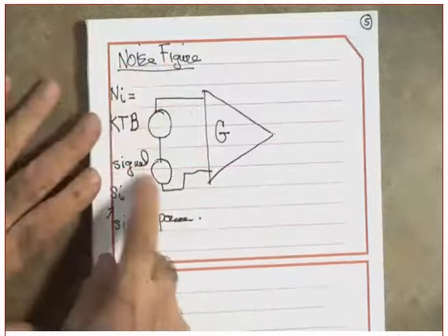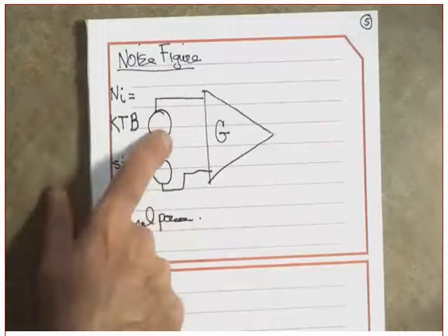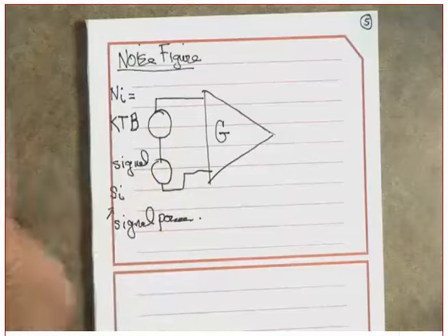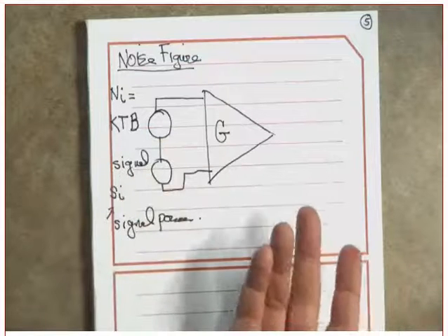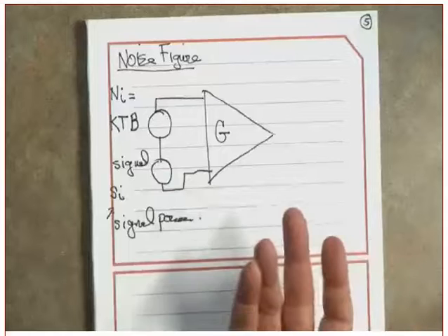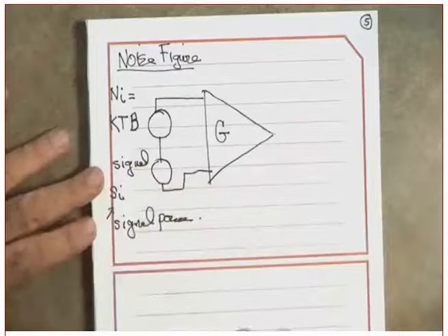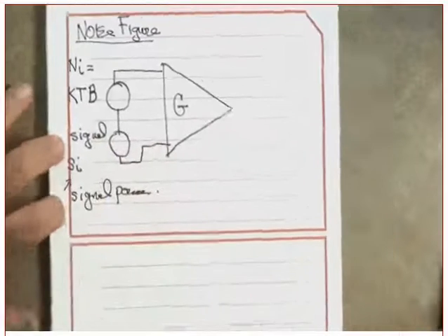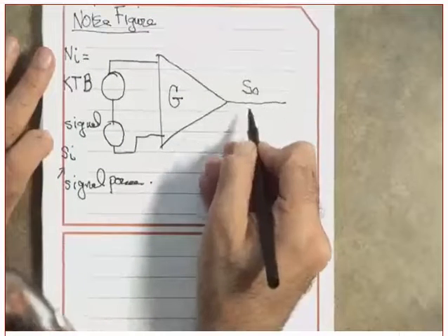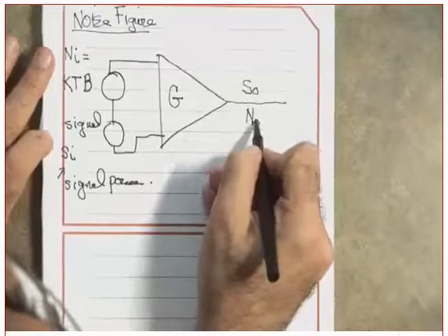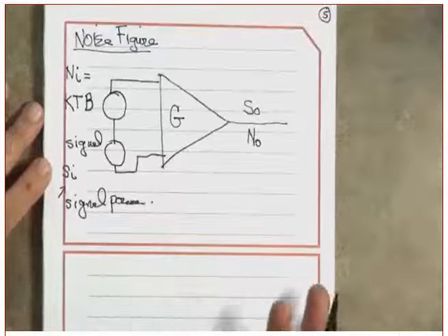So we have an amplifier. You applied the desired signal. This is the signal, useful signal. And there is a noise. Could this noise come from an antenna? It can come from the antenna. Are you following me? Not from any resistive source of noise. This one, I'm lumping it as KTB. Clear? Okay. I am measuring the output signal power and the noise power.